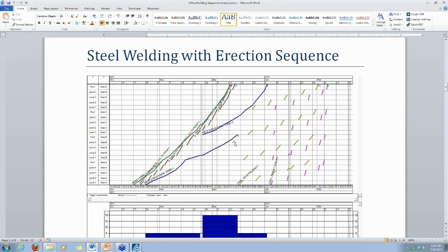By defining 2 crews of 9 workers and splitting those between areas A and B and C and D, we minimize the overlap and the total resource demand, but we also unify the crew size within each of the individual workflows. By splitting those locations into 2 crews, we can start the second crew earlier, which brings that end date for the phase closer to the originally planned date.